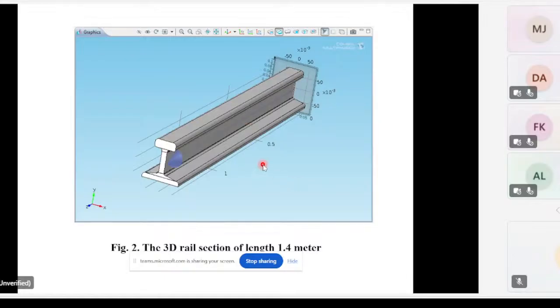Here, this is a plane strain situation. Why? It's very long. So actually, strain along the third direction is almost zero, because a very small strain is divided by a very long length. So it's almost zero, negligible. That is called a plane strain condition. So it's the plane strain fracture toughness you have to determine. That's why you have to call in K as well as J.